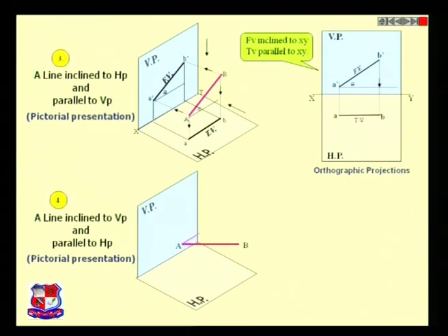Now we will take the projections of it. We are having some sort of angle with the VP. We are seeing it from the top view first. As you can see over here, we have taken the projection A and B. We are seeing it from the top, so the nomenclature would be small a, small b. Now, how can this front view be adjusted? A front view can be directly traced in between the AB line, but it would always be on the smaller side. If we are straightening any inclined line, then it would have a shorter length. The same rule applies over here.